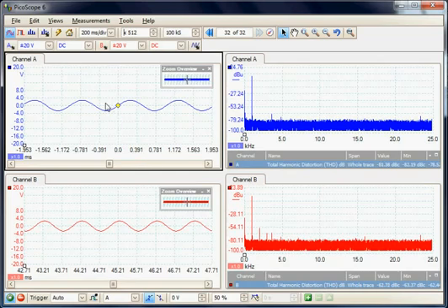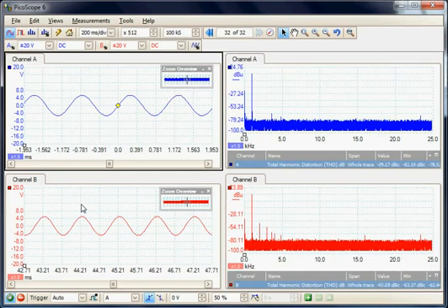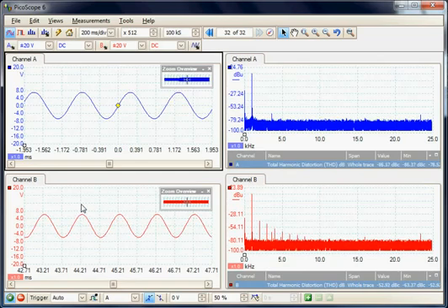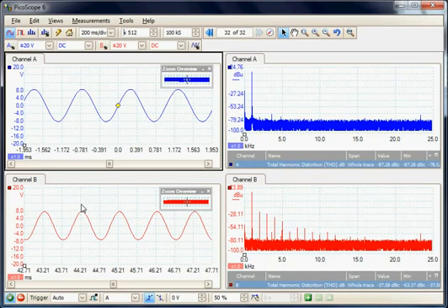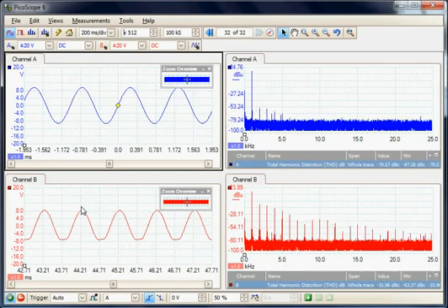We're now going to increase the gain of the amplifier and drive the channel B in fact into a distortion. So I'm increasing the gain on the amplifier, and now we can see the power across the 15 ohm loads increasing, and eventually now we've driven the channel B into distortion. This is in fact a bias fault on the output amplifier of channel B.